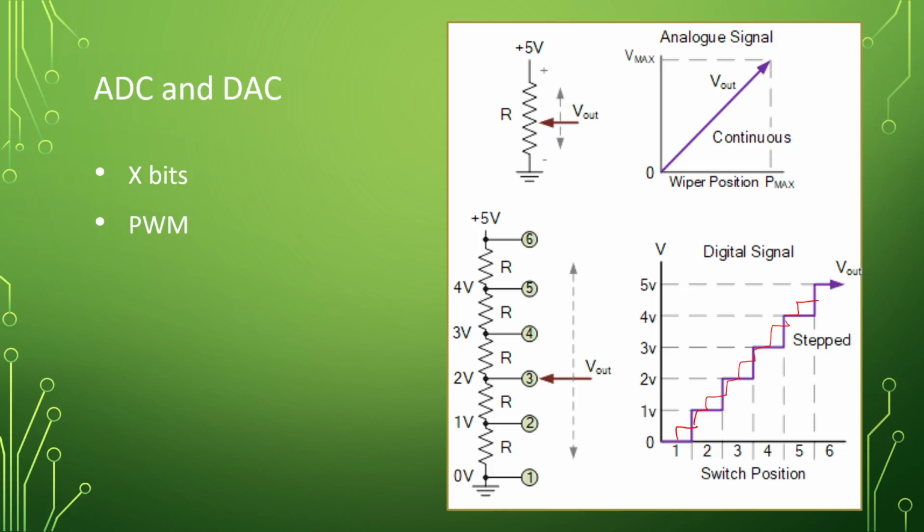So that resolution is very important for you, and it's a game that you have to play. It's like, I need high resolution, I need to be able to tell a quarter of a degree or an eighth of a degree. Well, you have two options. Option one is find a better ADC. So instead of that 8-bit, you go to that 10-bit or 12-bit or whatever, however many bits you need. That would be option one.